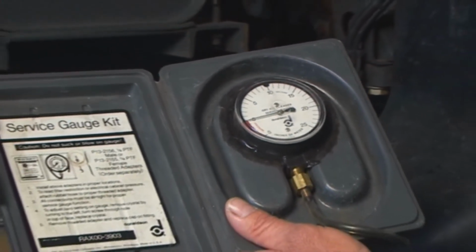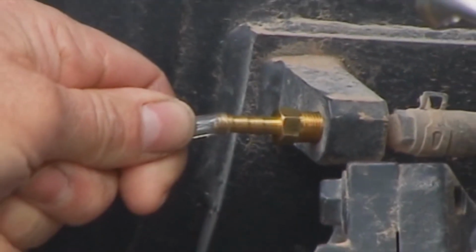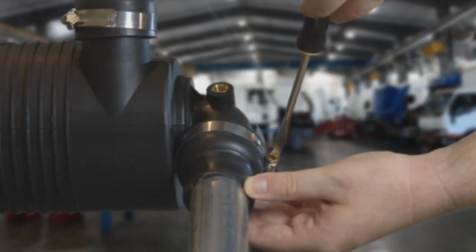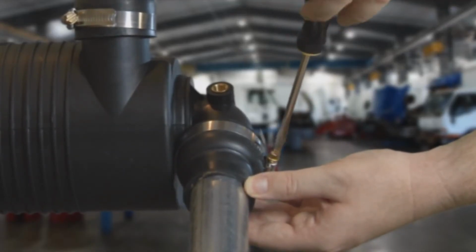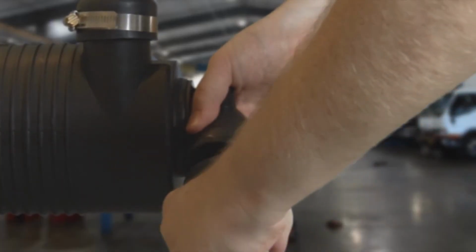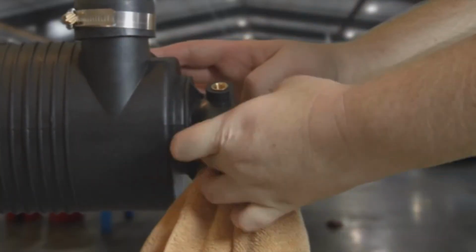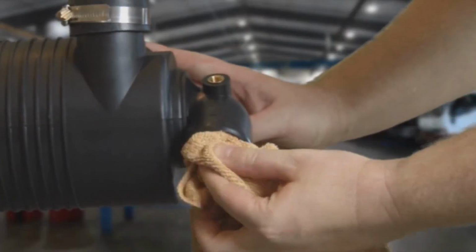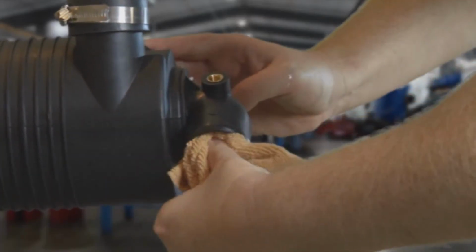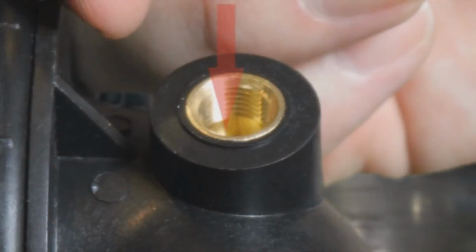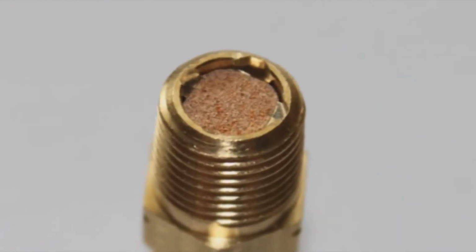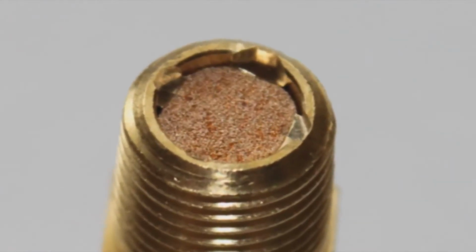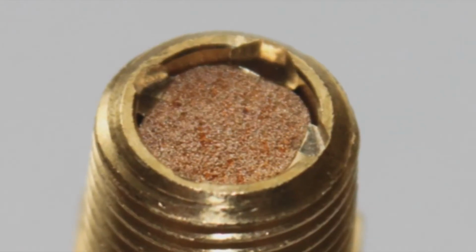Shut off the engine and continue with the following steps. Remove the test indicator connection at the indicator port. Loosen the clamp to the outlet hose connection of the air cleaner and disconnect the rubber connector. Place a rag into the outlet of the air cleaner. Placement should be past the point of service indicator fitting. Now look into the service indicator port and note the small brass filter. This tiny filter is critical to prevent dust being drawn into the engine's clean air path in the event the service indicator becomes damaged or missing.